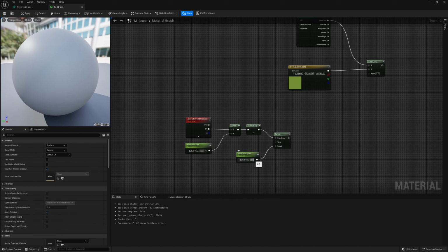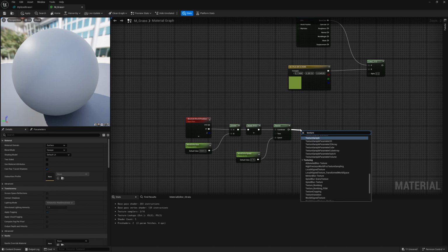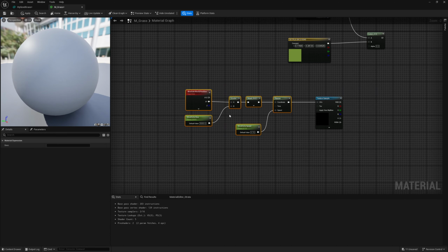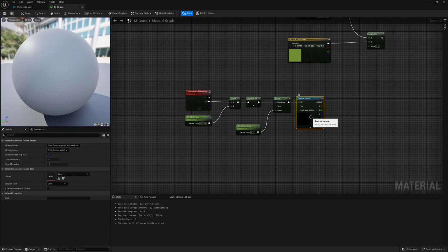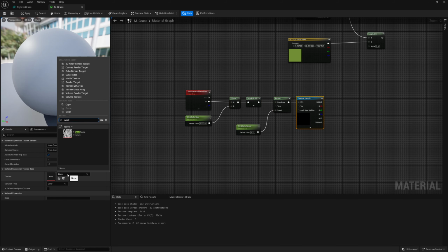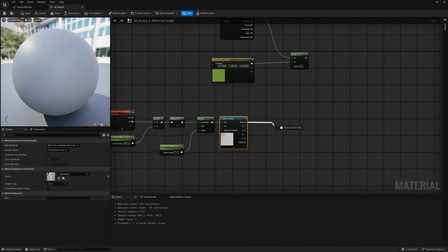Wind color speed, and we'll give it a speed of 0.005. Very slow for now, and we'll plug that into a texture sample. This information is basically saying you have your size of your texture as well as what it's doing, which is panning across. That we are panning the UVs across this texture. So we'll look for the wind that we made. Imagine that just moving across.